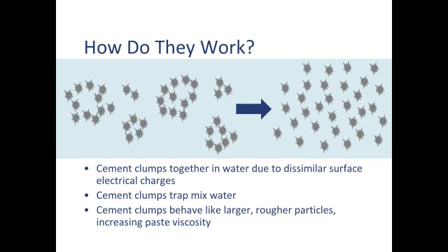And very tiny particles have unique characteristics that are not shared by large particles like sand and gravel. When you get down on the microscopic scale like this, these are 10 micrometer size, you get electrostatic properties. There's static electricity, if you will, that becomes a dominant force in the microscopic world of cement particles. And your pigment particles are similar sizes, and your pozzolans are similar sizes, and things like that.